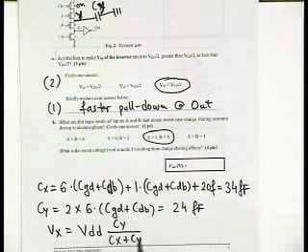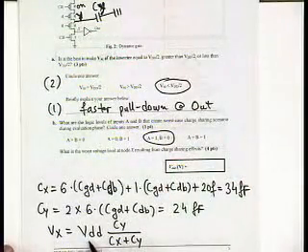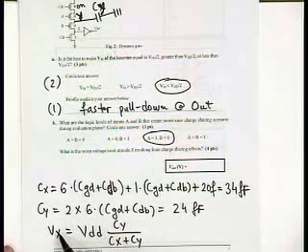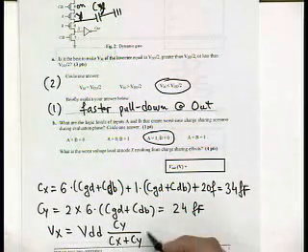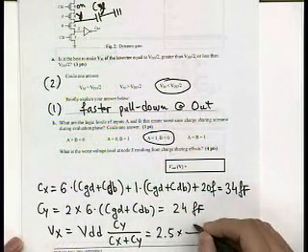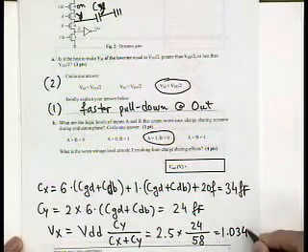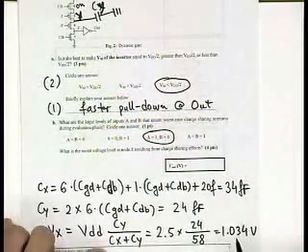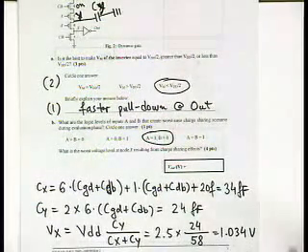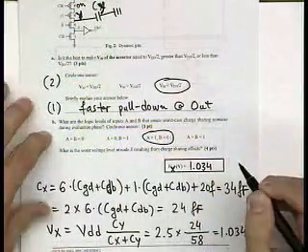And so basically you just balance the charge. Initially the charge was stored on this capacitance Cy, and the amount of charge was proportional to the voltage applied to that node. So it's VDD times Cy, it's equal to Vx times Cx plus Cy, and that is equal to 2.5 times 24 over 58, that is 1.034 volts. And now you see that the assumption was correct, because Vt was probably somewhere around 0.5 volts or so, so delta Vt is indeed greater. So that was set up, and this Vx is 1.034.